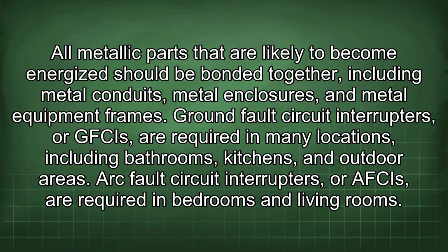equipment frames. Ground fault circuit interrupters, or GFCIs, are required in many locations, including bathrooms, kitchens, and outdoor areas. Arc fault circuit interrupters, or AFCIs, are required in bedrooms and living rooms.